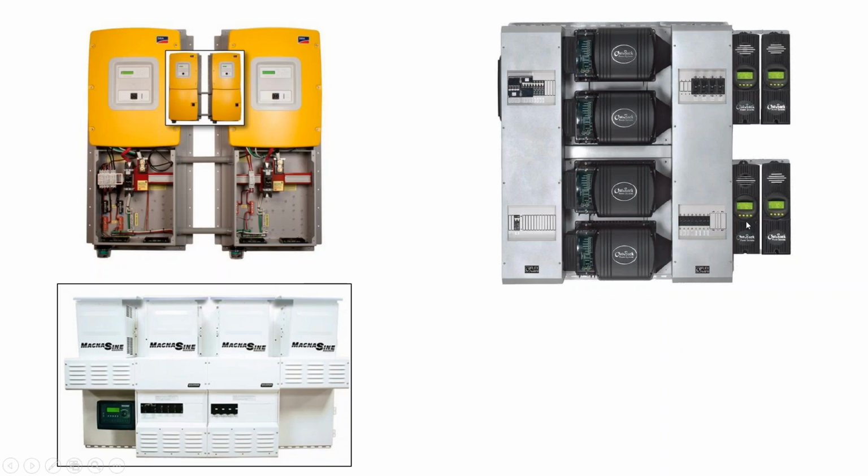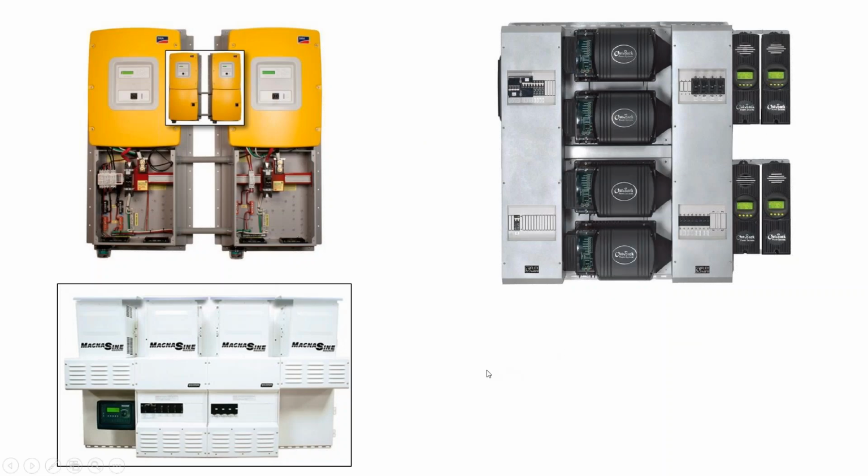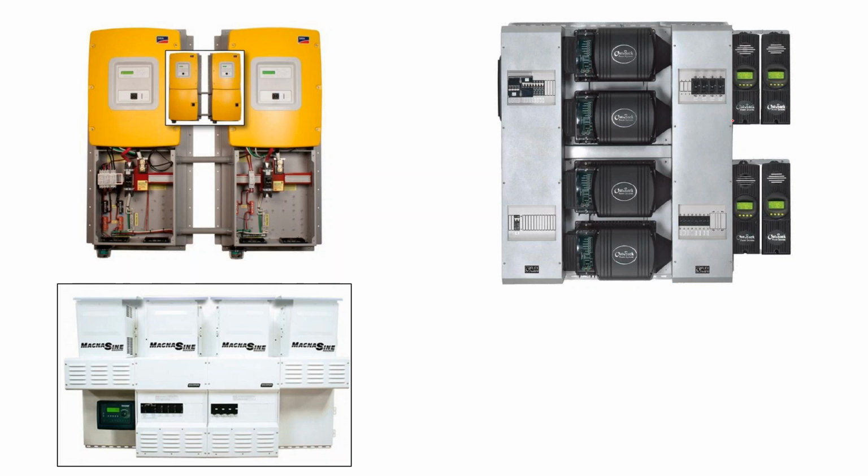And so here, on the picture on the right with our Outback inverters, we have the charge controllers being wired in parallel, and that's probably occurring at this point right here where we've got 4 breakers. We probably have the charge controllers coming up onto a common DC bus that the battery inverters then get wired into.